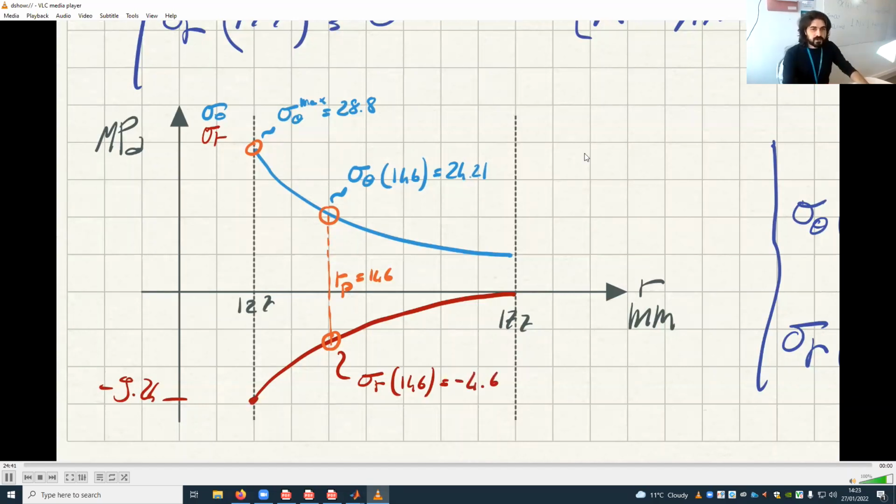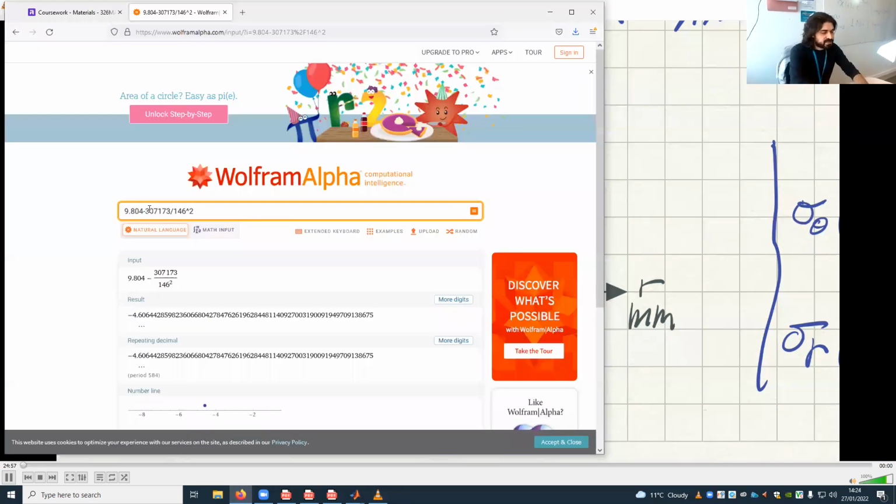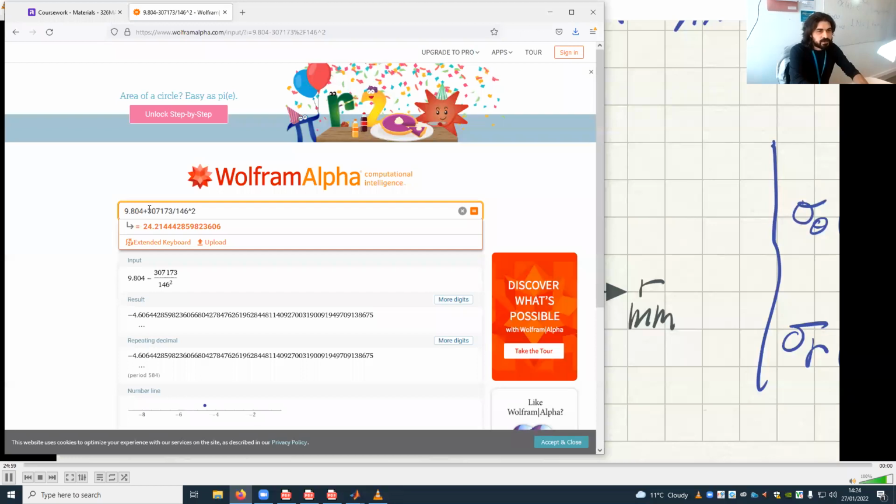Okay, and just for completeness, I also want to know what's going on here. How much is the external hoop stress? Very easily again. So the hoop stress, I want a plus sign, and I want it at 177. So this is 19.6. This one here.